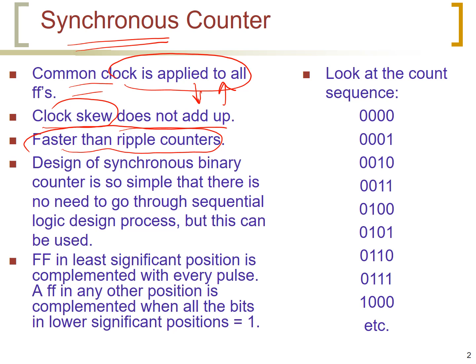The design of synchronous binary counters is so simple that we don't need to go through the sequential logic design process which we described earlier. However, we can use the same process if we want. The feature of the counters usually is as follows. The flip-flop in the least significant position is complemented with every pulse.